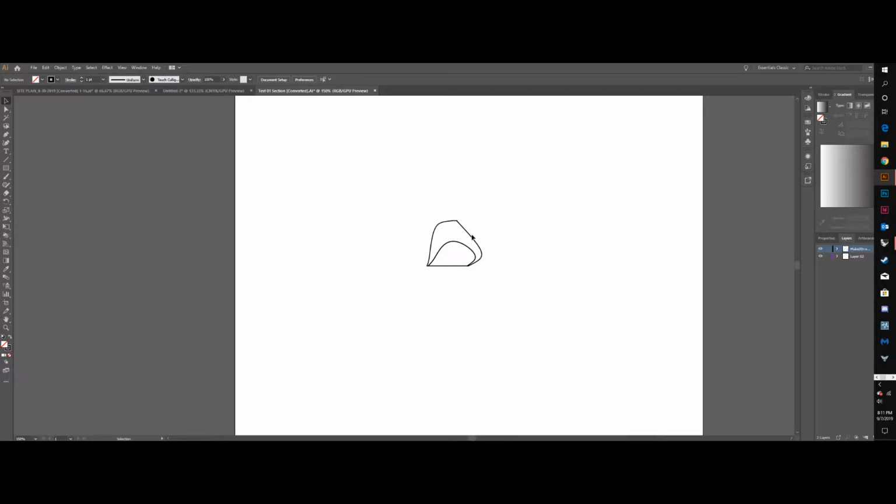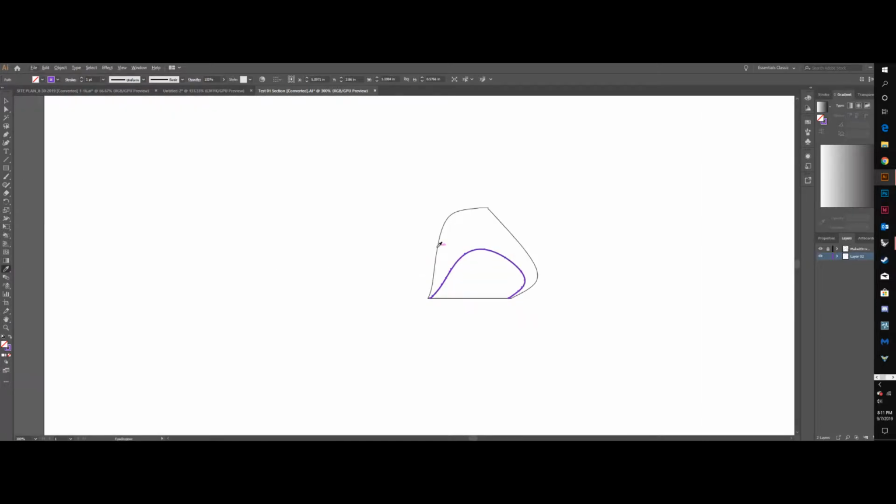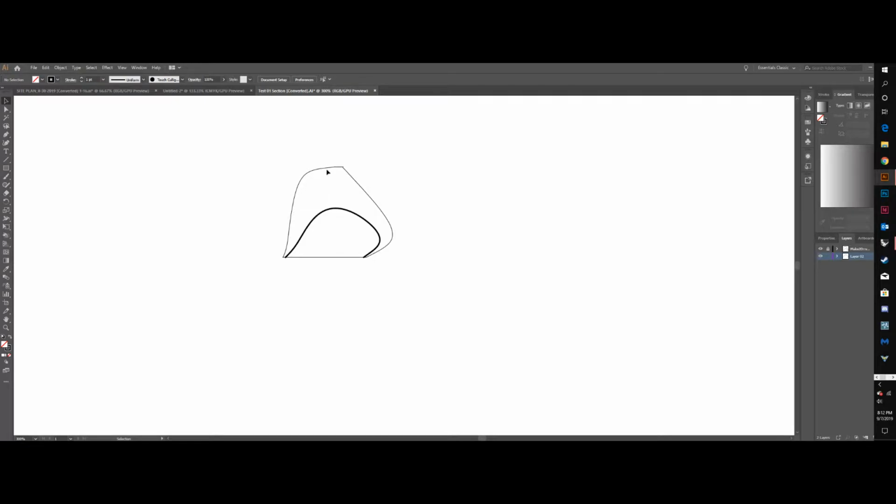I can easily post-produce this drawing by selecting the layer that is all of the lines that are not cut lines, and locking the layer that is cut lines. So I'm going to select all these lines that are not cut lines, make them really thin, 0.25, and then the cut lines I will make, say, 1 point. That's fine. And I will just use the standard black, change that back to 1 point. And there I have a drawing of a very strange object in section.